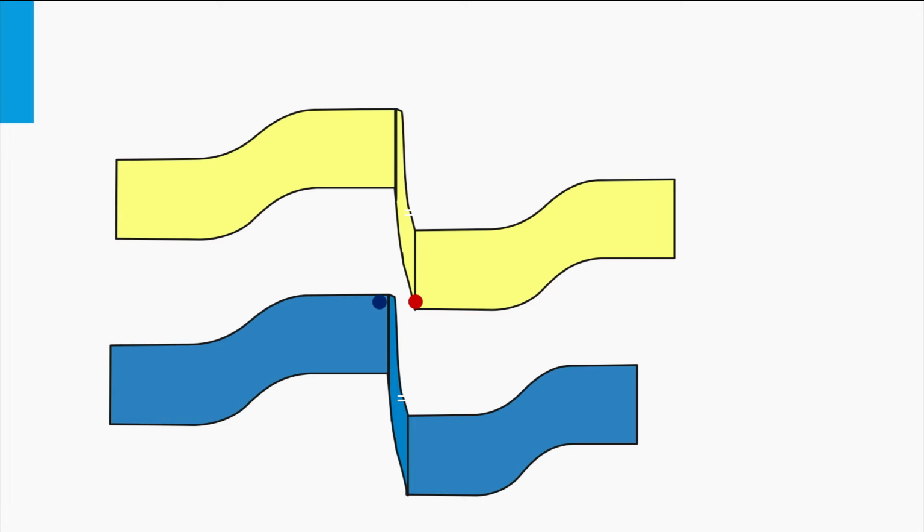The creation of such a reverse junction can be prevented by the inclusion of a so-called tunnel junction. It provides a low electrical resistance and has a high band gap to prevent any parasitic absorption losses. The high band gap tunnel junction is relatively thin. It means that the valence band at one side is lined up with the conduction band at the other side of the tunnel junction. The depletion zone of such a junction is extremely narrow. As a result, the slope of the valence band and conduction band are so steep that the electrons from the N layer tunnel through the small barrier to the P layer, where they recombine with the holes.